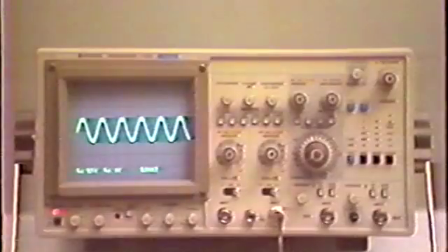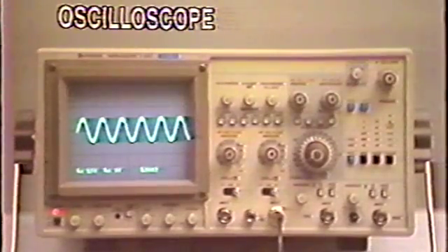In Part 1, we will explain the tools required for repairing and adjusting the Casio tone and how they are used. When ordering these tools from Casio, please include the code numbers listed in the textbook. An oscilloscope is used to observe the waveforms generated by various sections and is indispensable for repair of the Casio tone. 100 MHz type is recommended.